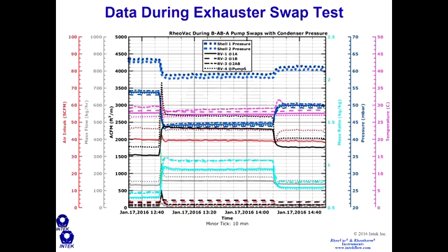So right here, we turned on a vacuum pump, and you can see the total volumetric flow rate increase. We go from 1,500 cubic feet per minute all the way up to 2,500 cubic feet per minute. So we've turned on a vacuum pump. We've gone from operating pump B here to pump A and B here, and then pump A over here.